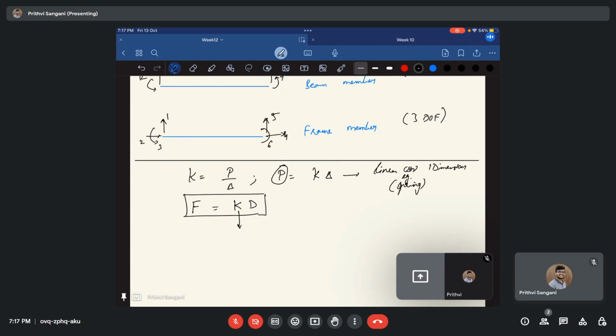But if we can generalize each condition and derive an equation, a generic stiffness coming out of each matrix, each problem, then we can apply the same thing to all the systems and derive the forces. We can derive the reaction forces, in turn find out the internal forces, and at the end draw the shear force diagram, bending moment diagram, etc.